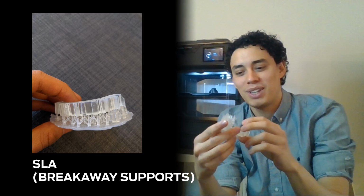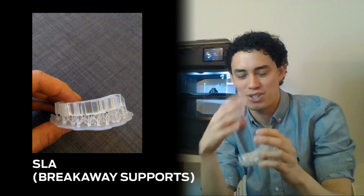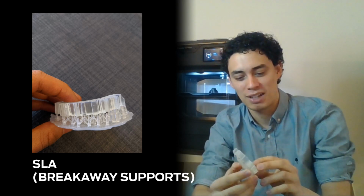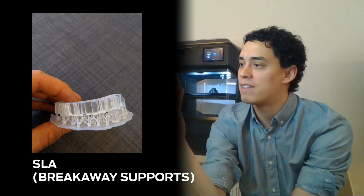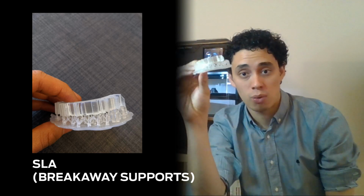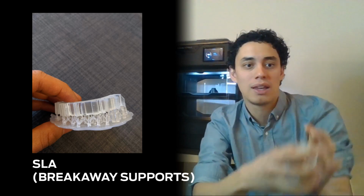This part was actually meant to be a sculpture. It was an abstract representation of time passing by, but anyways, an old project in a previous company that I worked for. But as you can see, the elements that I was talking about before become very evident here, such as you cannot use all supports other than breakaway. So the printer will create these little tree structures to support the part.